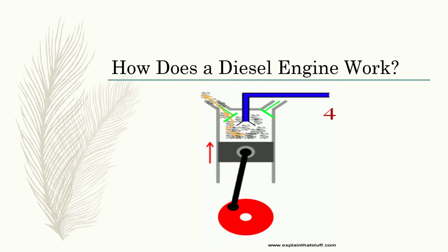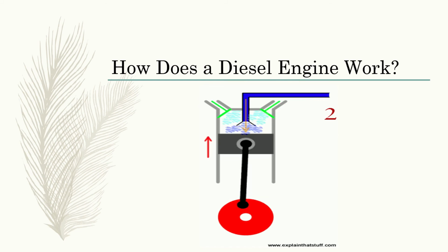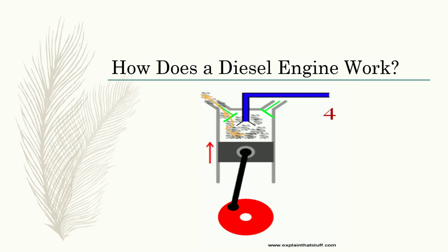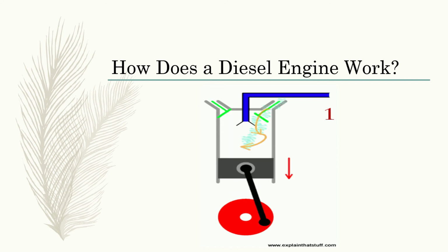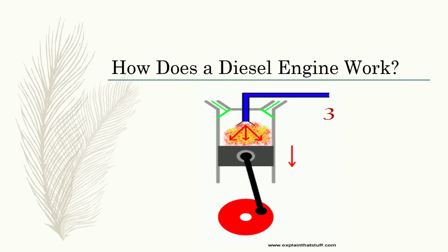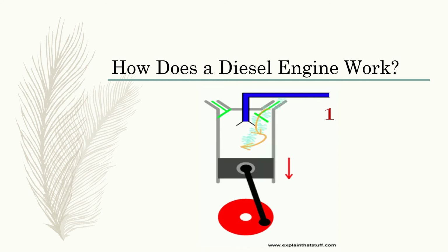We all know that a piston is connected to a rod, crank, and cylinder, which form a mechanism called the slider crank mechanism. Here, the linear motion of the piston transforms into rotary motion of the crank. In an IC engine, this mechanism is properly supported in an engine block, with the cylinder head, valve, and fuel injector fitted above the engine block.